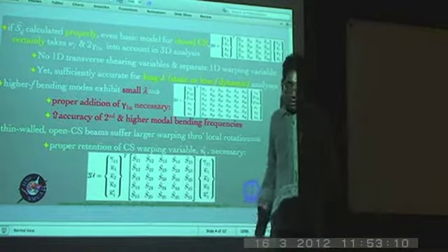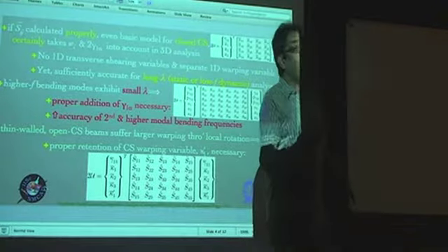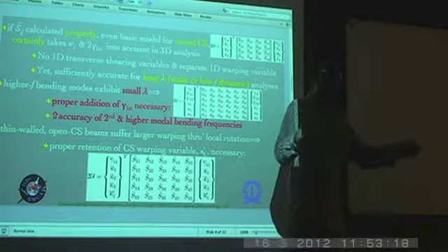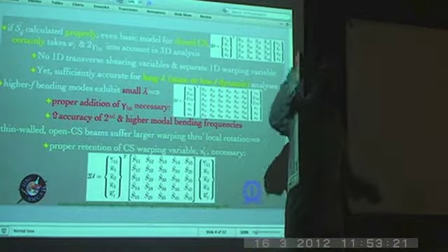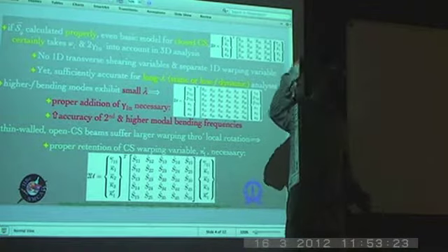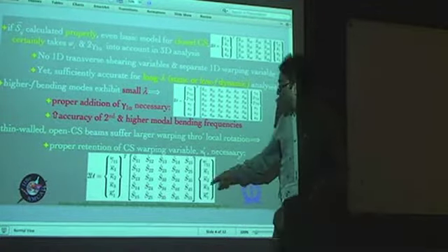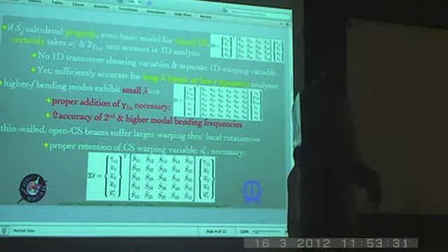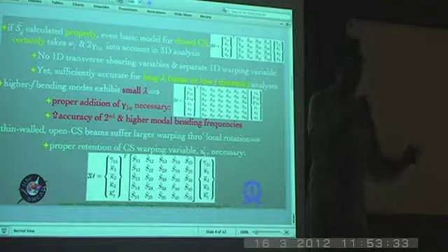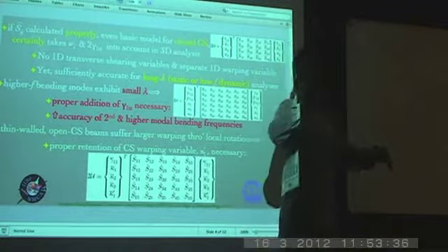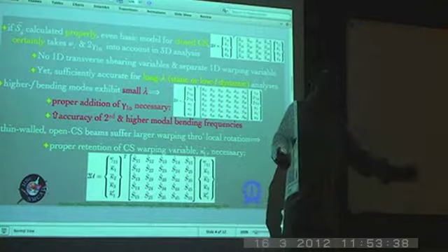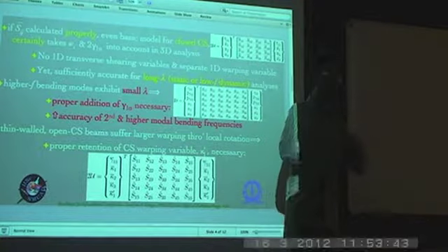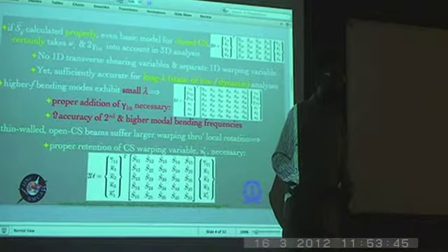So probably in some situation where, let's say, the bending stiffness is very low in one particular direction, for example in the case of a strip, when you go to a higher order approximation, not even first but maybe second or third, it is possible that you might get kappa 2 prime or kappa 3 prime, but the source of that is basically the warping derivative with respect to x1. In the case of plate or shell, you could have derivatives of w with respect to x1 and x2. Okay, so those can come into the picture in the 2D model that you have for the reference surface of the plate or shell.